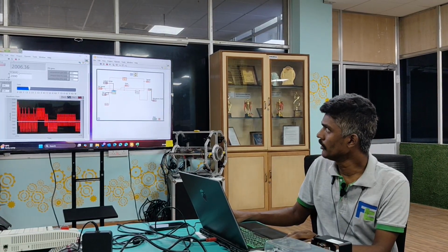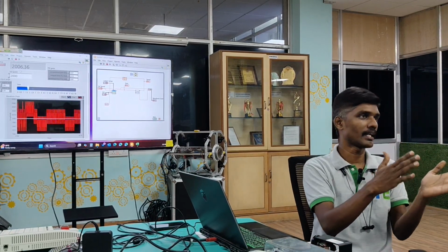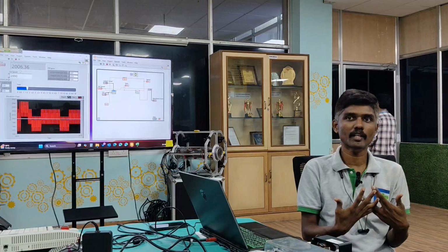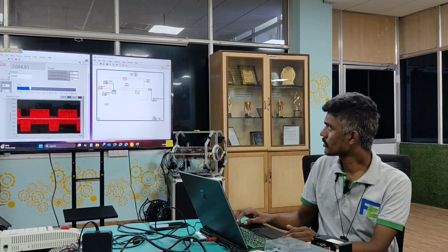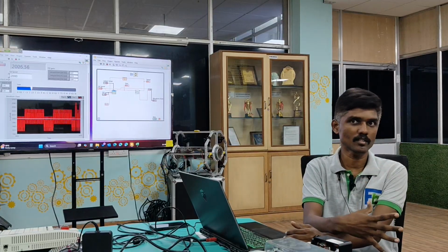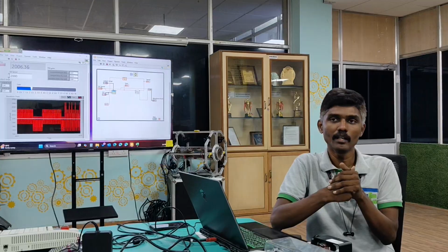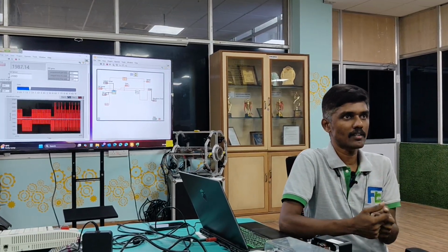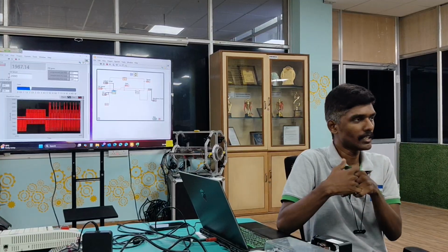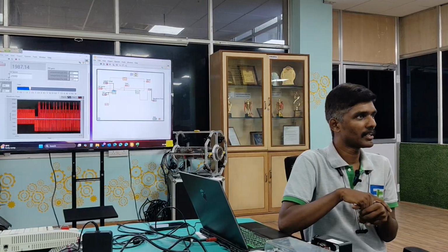Now my error will be 1987, something like within 30 RPM my error was reduced. Initially I was unable to get the error, then slowly you are able to tune it. For this system, since it is a very linear system, you can achieve the set point by using only proportional and integral gain values. When you have actual systems, you will start facing disturbances, and then only you will touch all your proportional, integral and derivative gain values.